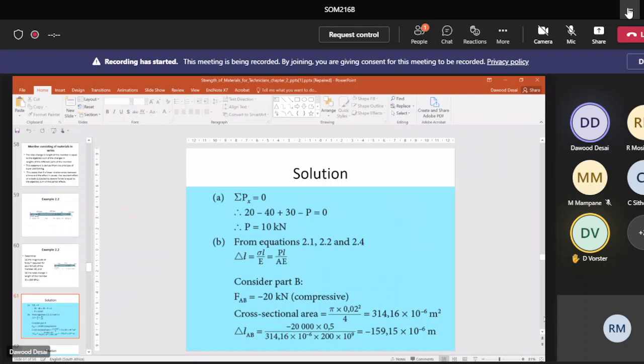Right, here's how it looks. This is a section through, so you can see one pipe inside another pipe. Okay, no problem. Rule number 1: write down the two governing equations that concern this problem. You can draw a simple sketch if you want, but the most important thing is to write down the two rules for axial deformation. Very important. Right, there are my two formulas. What are you going to say now? Force in steel is equal to force in copper.